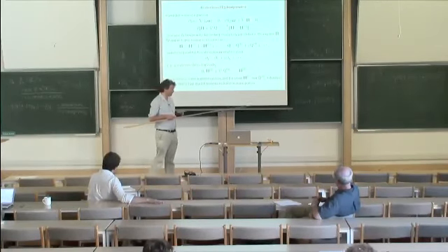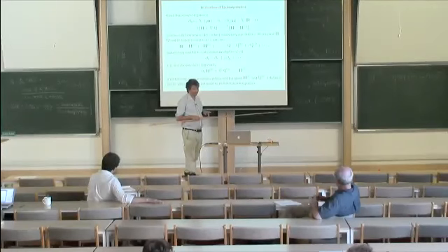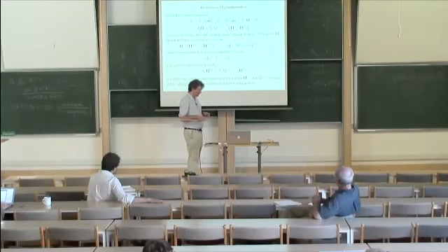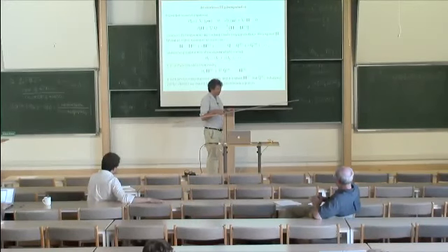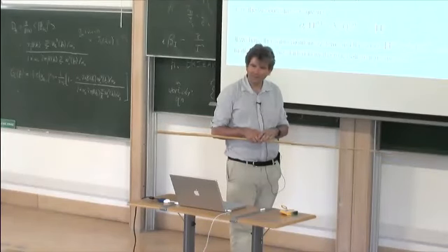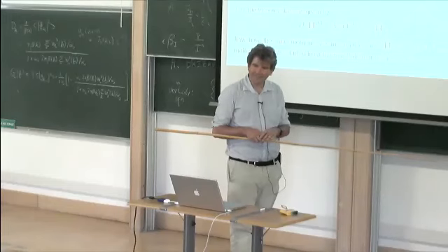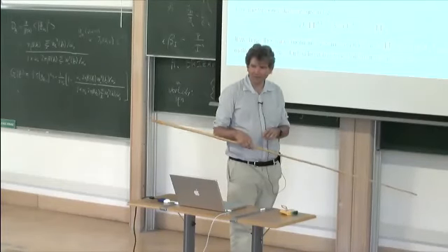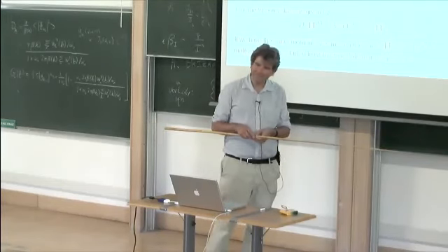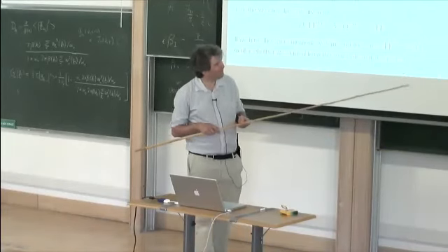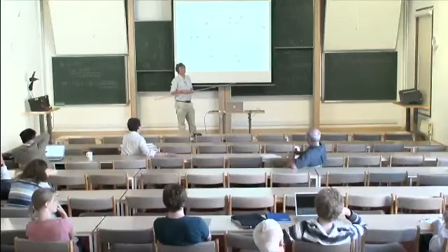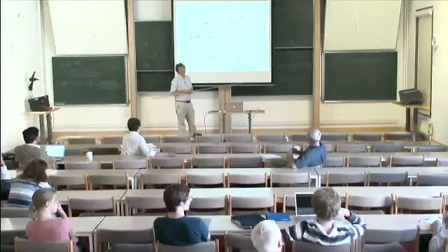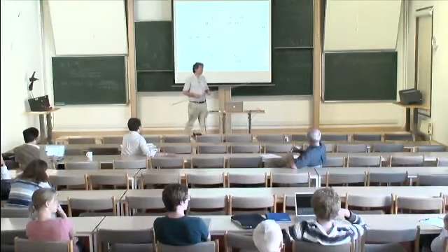So if you were doing real kinetic theory, you get stuck there, but in discrete kinetic theory, you can decouple the thermal speed from the particle speed just by changing the equilibrium. So I can do the limit where thermal speed is less than the fluid speed, and both are much less than the particle speed. So in principle, I can converge to Navier-Stokes-Fourier for whatever Mach number you want. But the particle speed is the speed that they jump between these lattice points, you know, delta x over delta t.